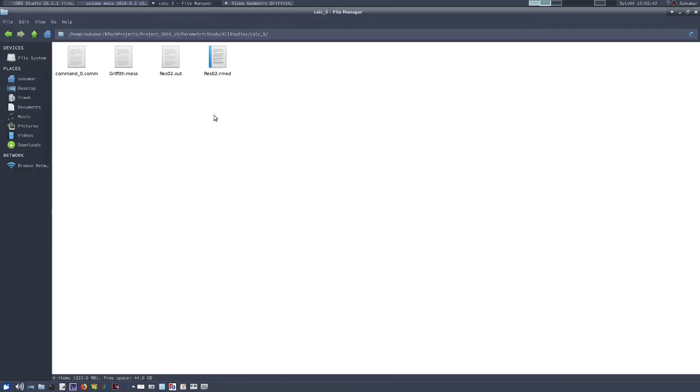Once our results are out, we can go to the folder which we created during the setting up of our study. These are different calculations for each set of parameters, and we originally gave 7 calculations, serially named calculation 1, calculation 2, calculation 3, etc. However, during the actual execution in astk, they need not be taken up serially. It may happen that calculation 6 will be done first, then calculation 2 next. So that seriality is controlled by the system, not by the user.